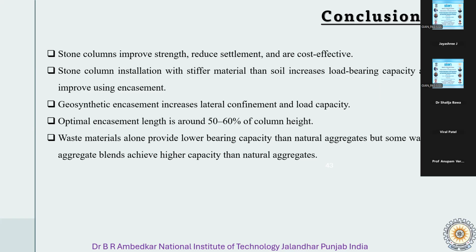And generally the geosynthetics come here. Okay, so they significantly enhance the performance by confining the stone columns and allowing them to carry more load. And the optimal encasement length is around 50 to 60% of the column height.